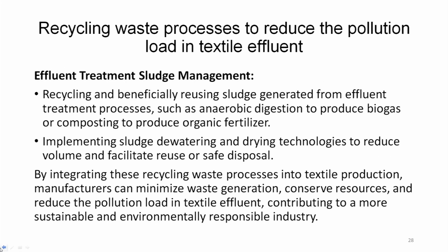Effluent treatment sludge management. Recycling and beneficially reusing sludge generated from effluent treatment processes such as anaerobic digestion to produce biogas or composting to produce organic fertilizer. Implementing sludge dewatering and drying technologies to reduce volume and facilitate reuse or safe disposal.